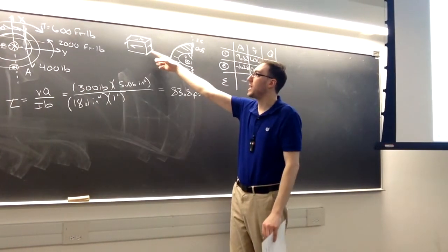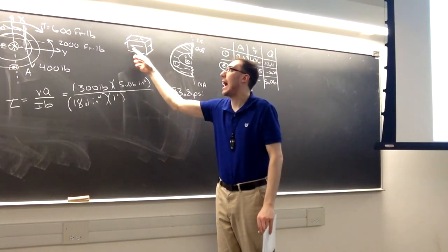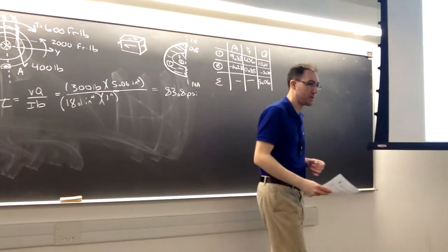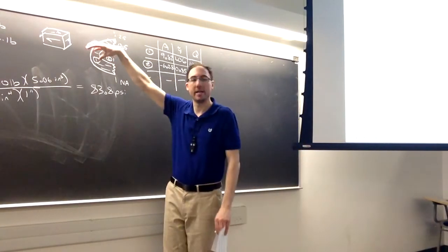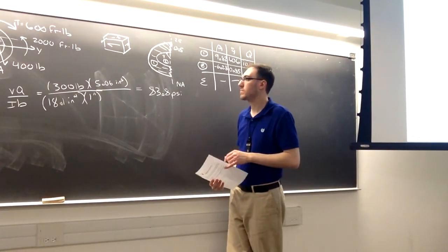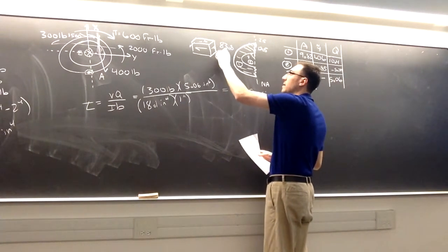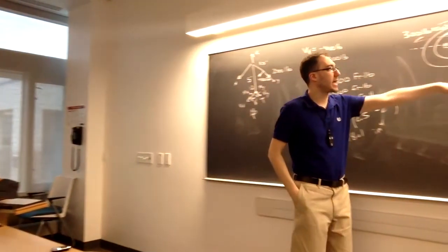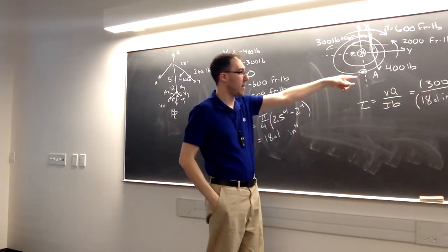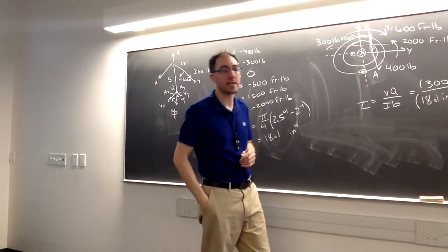So when we look at this, what we're going to see is these arrows always meet at the corners. That way, the rotation is balanced out. And it has a value, all of them, of 83.8 psi. All right, so the 400 is taken care of. It had no shear stress where A is. The 300 pounds is taken care of.